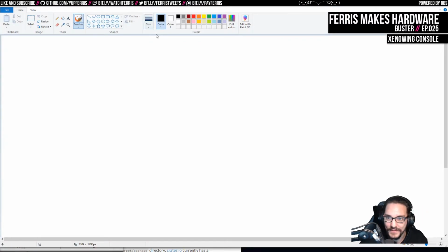I'm just going to attempt to redraw some of it in a really ugly way, but it's going to be fine. So the idea is that I have this display DMA, which we'll call DD. And this needs to read. I use arrows to say that this is a read port. That doesn't necessarily mean that all the data flows this way, because there's some signals for handshaking. So this needs to send the address, for example. So the arrow only means that this is the direction that actual data is traveling, even though there are signals as part of this arrow that are going to be both ways.